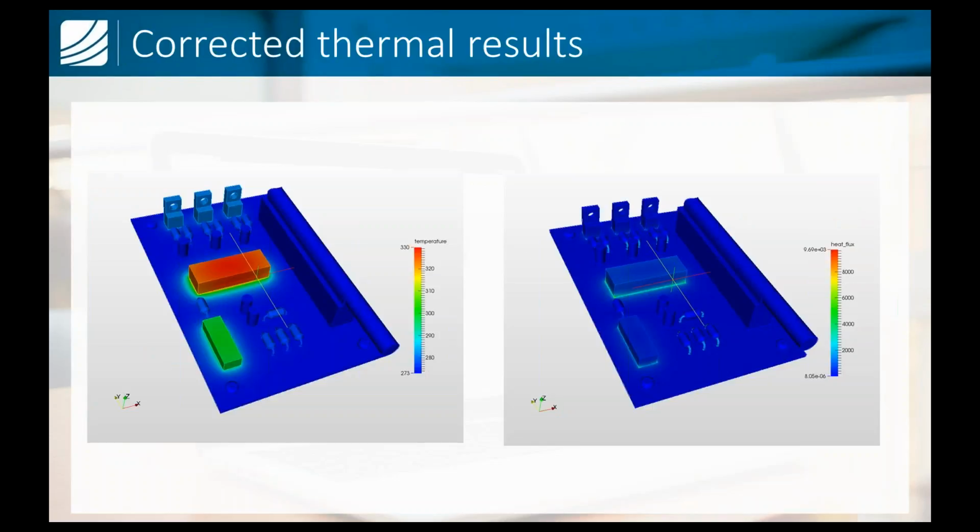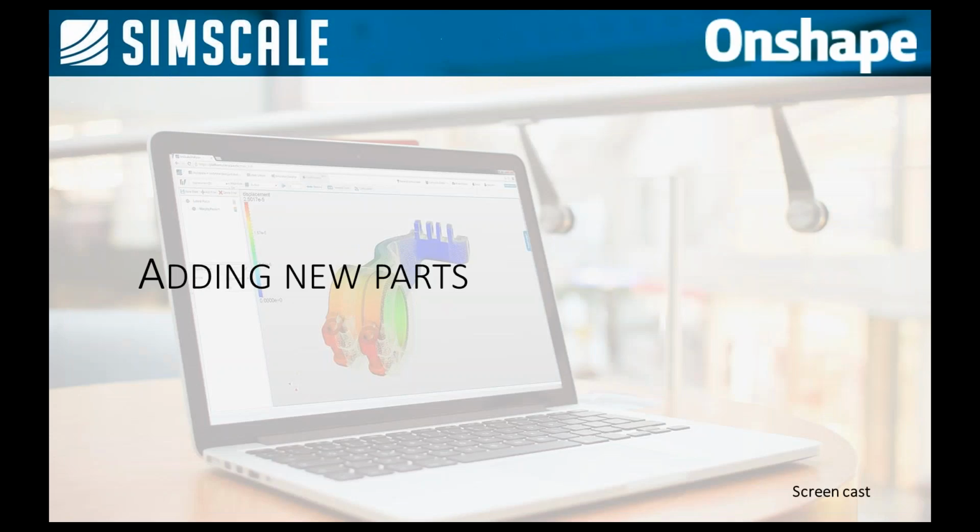And this was only obtained by selecting proper contacts and having the heat removed properly, not from below the elements. So we notice that this is pretty important. And also the heat flux happens between the electronics parts, and there is a lot more heat moving from the processor to the PCB board and later being dissipated by the convective heat transfer boundary condition outside.